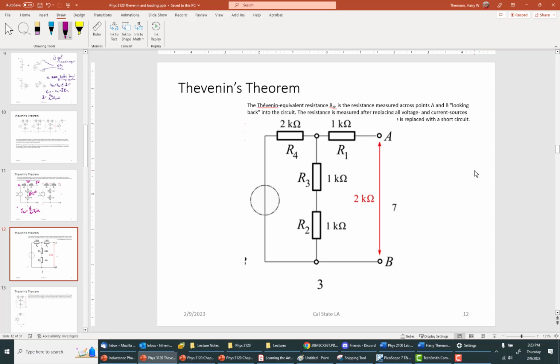Because we're assuming that the power supply is ideal, which they are to most degree, we simply put a wire there because R equals 0. That's a little different now. An ideal voltmeter has an infinite input impedance. An ideal power supply has a 0 output impedance.